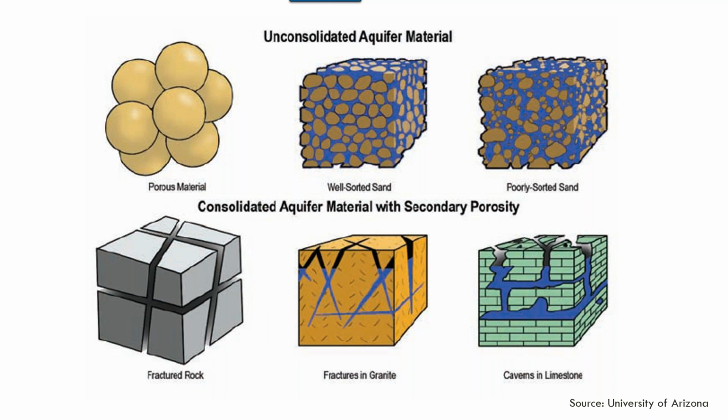But in most cases, when you are dealing with a bedrock well, you're dealing with fractures, and how much water is actually being stored depends on the interconnectedness of the fractures and the size of the fractures. So in southern Illinois, Indiana, and Kentucky, where you have a lot of caverns like Mammoth Cave and some of those places, depending on how high the water is in the ground, in the aquifer, you can have some pretty big areas with water availability if you hit those fractures.